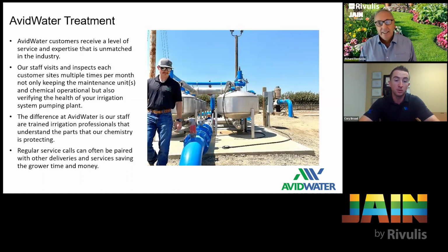Yeah, or hopefully it's a small problem, and then we can address it ahead of time. And maybe conversely, the other way is, hey, your pressure is down and your flow is up. Well, maybe you have a leak somewhere, or somebody left a valve on, or they're not running the system the way you think they are. We actually went out and did some irrigation consulting work on a field as recently as two weeks ago, and we were talking to the owner, and he's like, oh yeah, we have water in the north right now. We went over there and the water wasn't there.